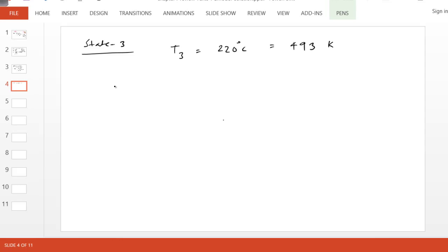So therefore, the actual turbine output is m dot (h1 minus h3). Recall, m dot h1 is the energy carried by the flow into the turbine, and m dot h3 is the energy that is leaving the turbine in an actual turbine. And so that becomes m dot cp (T1 minus T3) for the PG model. Again, from handout J you can figure that out. It's written under the PG model, these formulas.